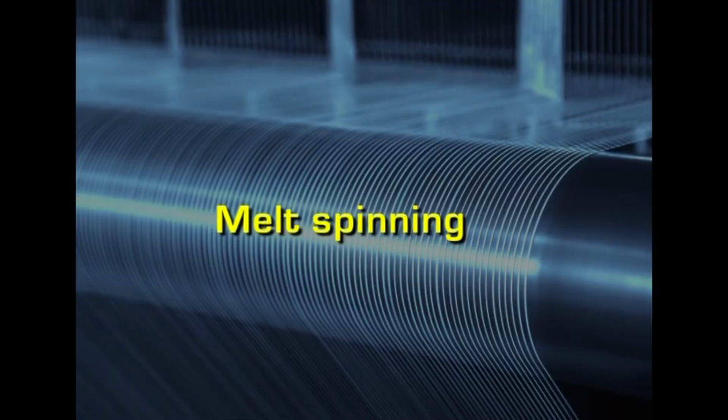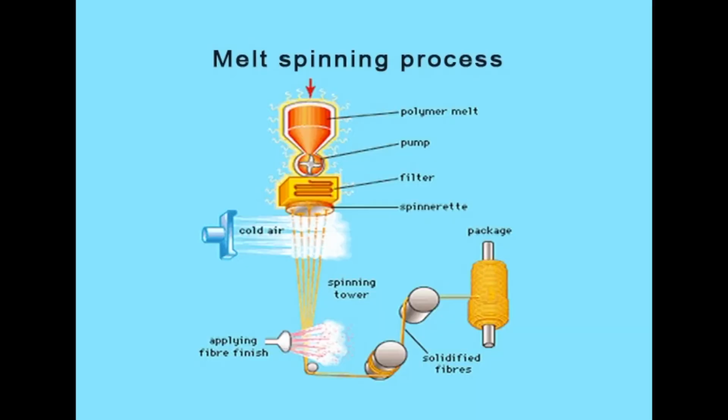Coming to melt spinning, this is the simplest method, because it involves only melting the polymer, extruding it through the spinneret and then cooling it in air. When it hits the air, it gets cooled and solidifies in the form of a very thin filament.